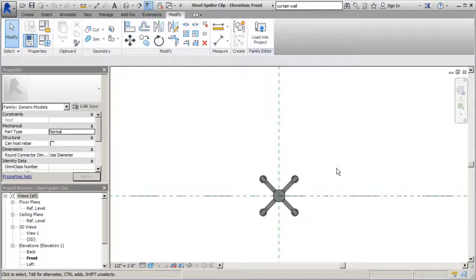So an instance parameter allows you to click on one individual item and change that one individual item's parameters. A type means if I change the parameter within that one item, the entire category or the entire type will have that change. And we want it to be unique for each piece. So it's not a hard fix, but it's important to know.